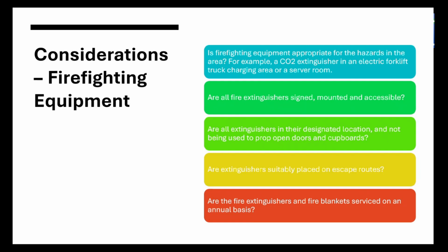It has to be photoluminescent so that in the event of a fire, we know we're grabbing the correct extinguisher. Mounted on the wall at a reasonable height so they can be accessed by people, and if required, wheelchair users as well must be considered. And accessible means they must just be unobstructed with goods.